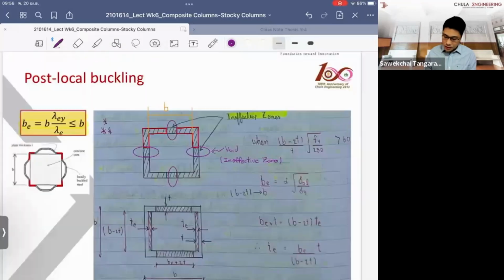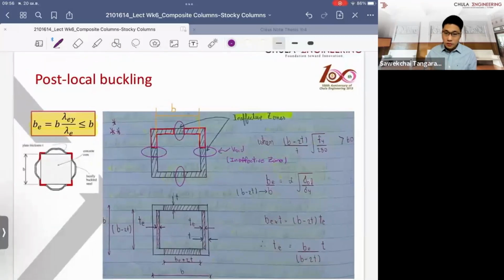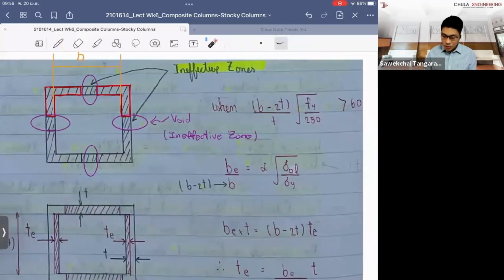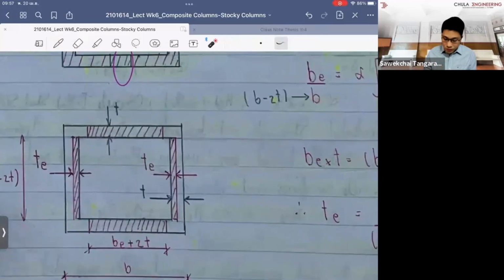When you do the stress analysis, basically you look at the strain and you try to change the level of the plastic neutral axis, and then you can draw the stress diagram. If there is a gap here, the calculation will be more tedious. The simplified method also gives you a simpler way to do it.